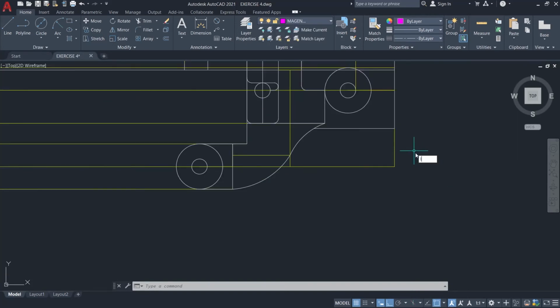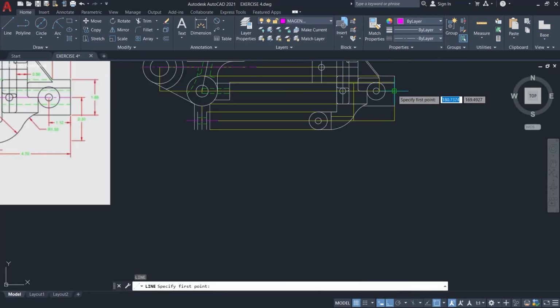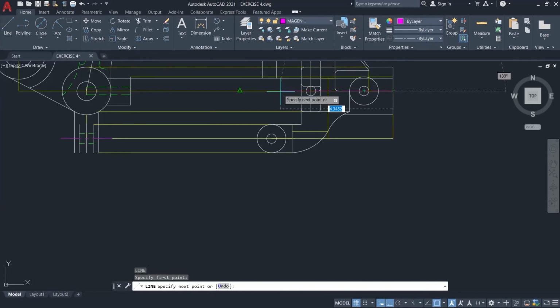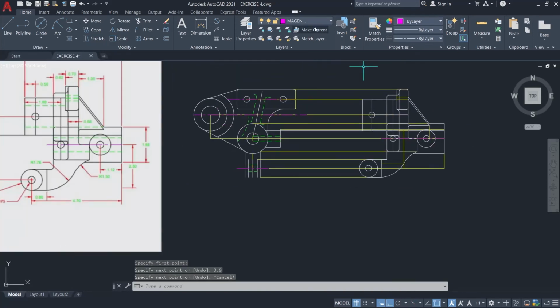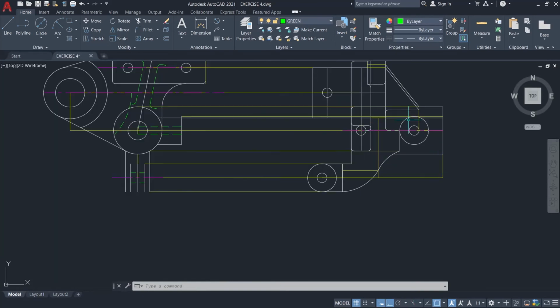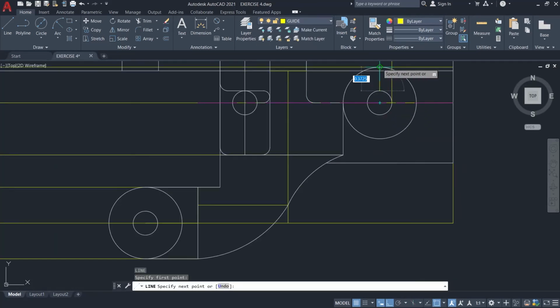From this midpoint, create a line to the left by 3.9 units using magenta color and center dash line type. Then, to create those green dash lines, first, make a guideline from the top and bottom of the inner circle up to the top and bottom of the outer circle. Then from its midpoint, create that green dash line and just extend it.